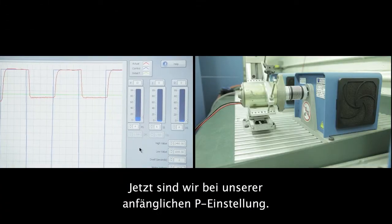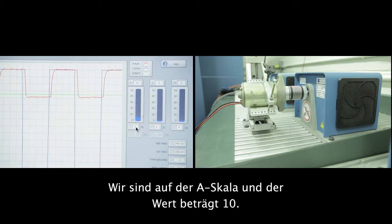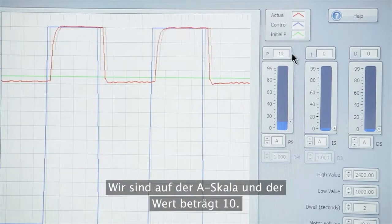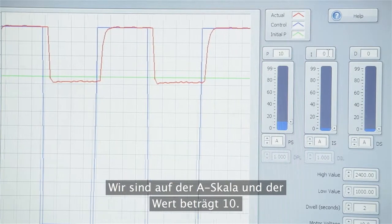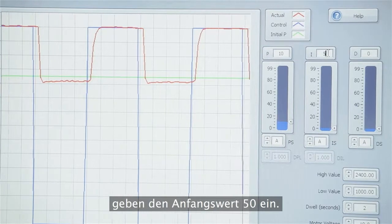So now we have our initial P setting. The scale is A, the value is 10. Now we go over to our I term and enter a starting value of 50.